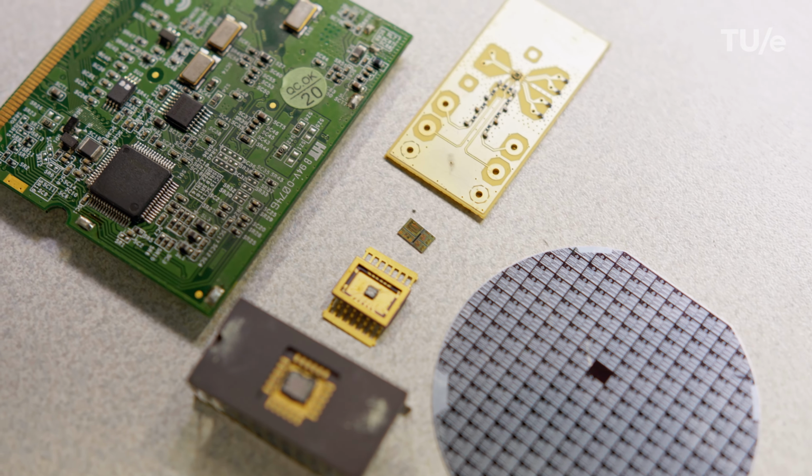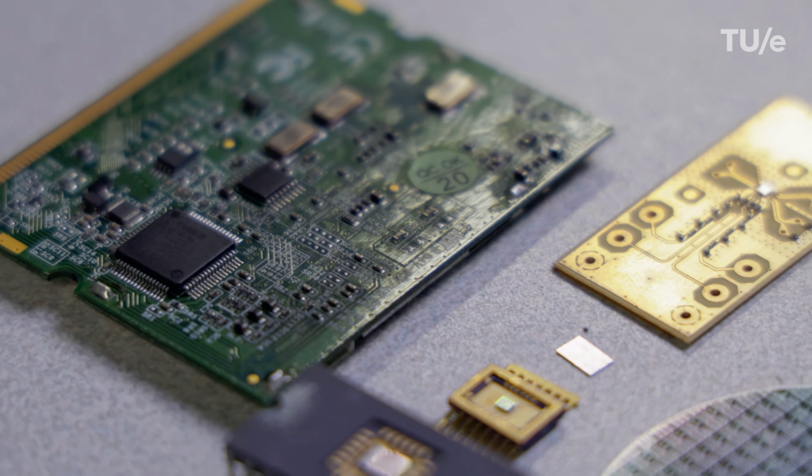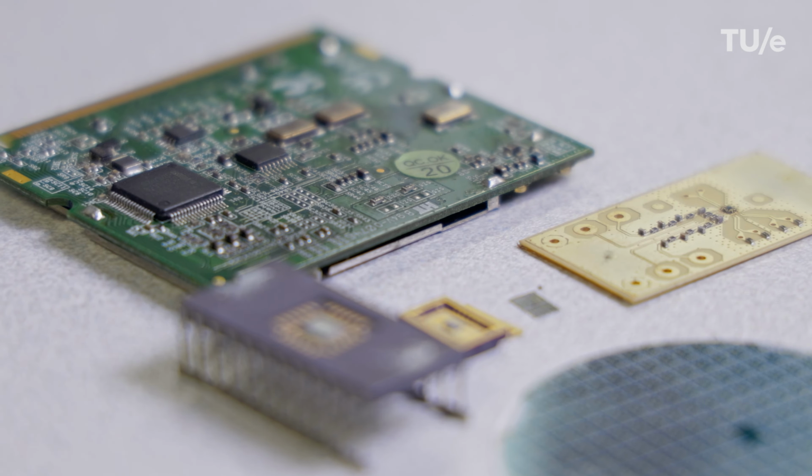Once your design is manufacturer ready, you can send it to the manufacturer. You will receive it back 3 to 6 months later. Only then can you measure your chip and see if it actually works. If you're lucky, you can produce your design en masse and embed it in cell phones and other devices. But you can also measure the chip in more depth and update your models, because that makes future design processes easier. And that is what we mostly do here at Eindhoven University of Technology.